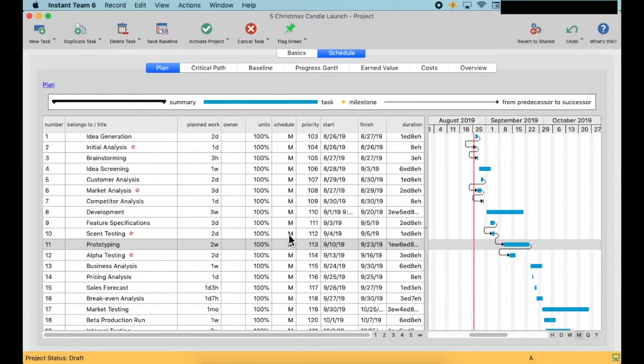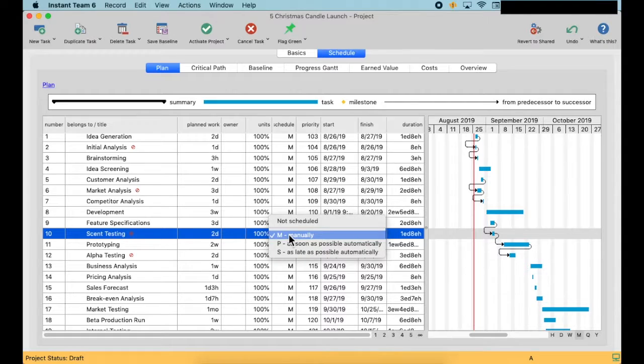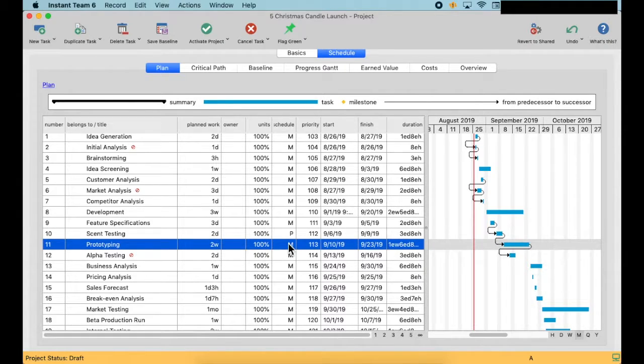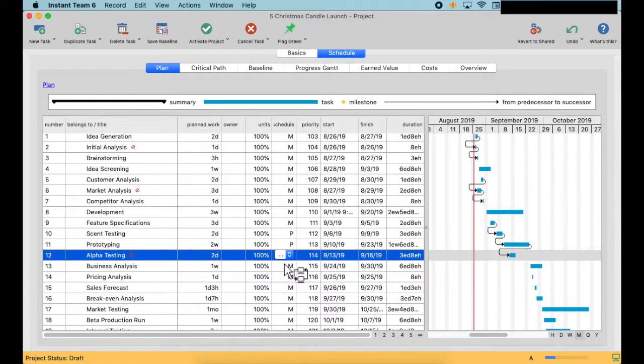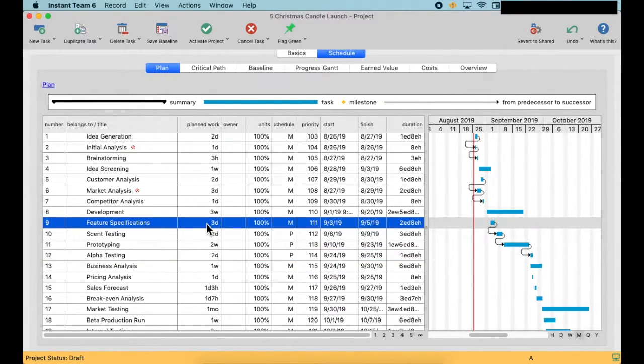By filling in the order fields P, tasks automatically move to the closest possible terms, so they start right after the end of their predecessors. And if we move one task in the string of tasks bound by predecessor-successor relations, then the other tasks in the string will automatically move too.